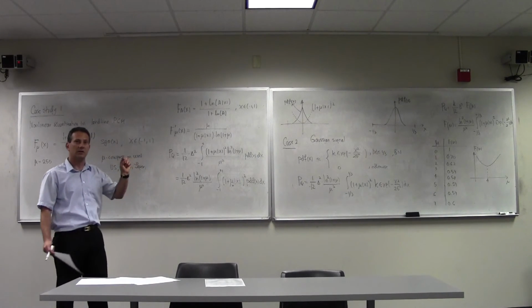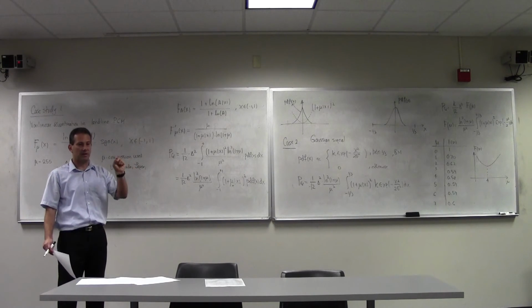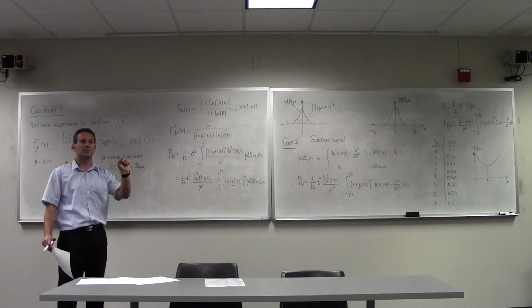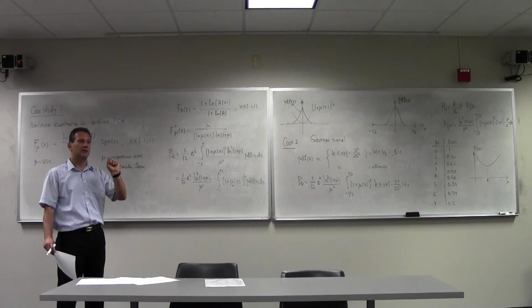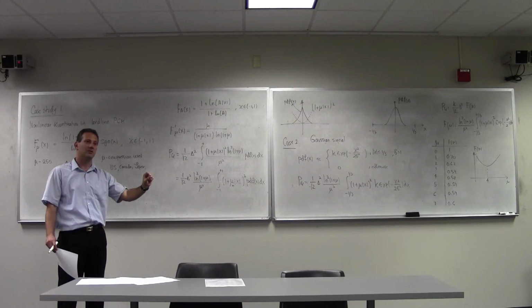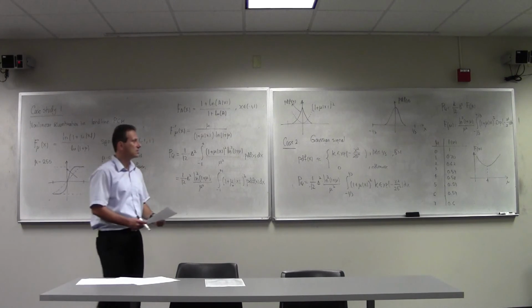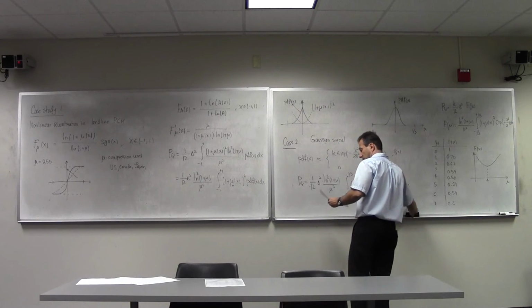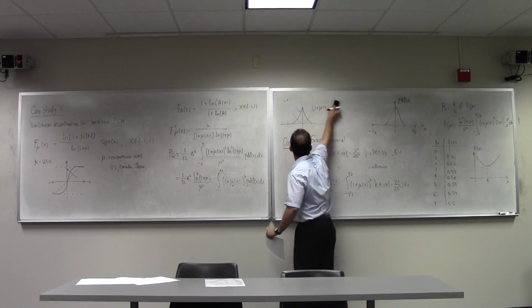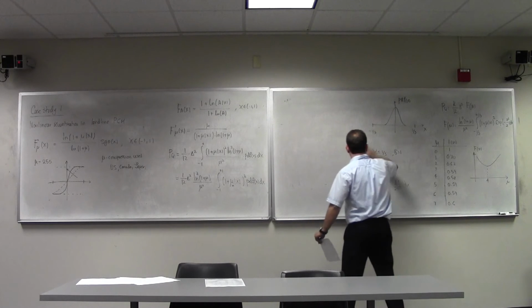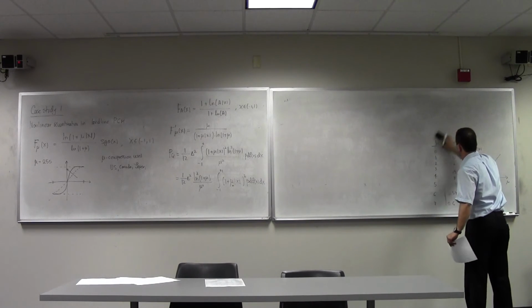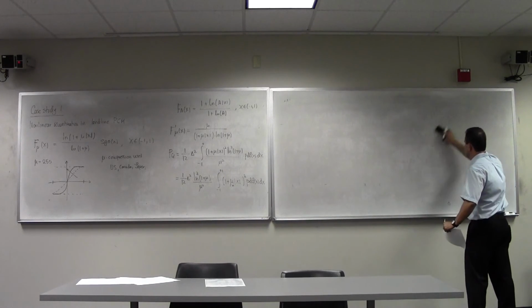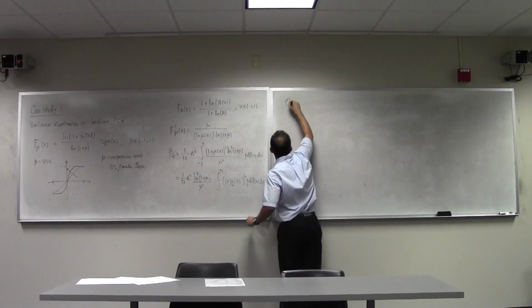In other words, we looked at last time and said, if I take a uniform signal and pass it through a uniform quantizer, signal to quantization noise ratio was 20 times log of Q, where Q was the number of quantization levels. Now, if we have a uniform signal and we pass it through a non-uniform quantizer, you expect that there will be some penalty, just like we had a penalty associated with a Gaussian signal from a non-uniform quantizer, right? So as an exercise, let's evaluate that as well. And this is going to be the second case. I'm going to leave this result here. So this is case 1 now.